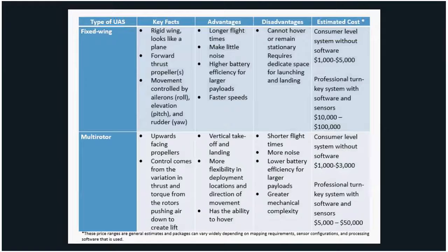Sure. Yeah, this is George. So it depends a lot on a few things. One of them is that if you didn't fly with an RTK system like Sam talked about earlier, it would be necessary to have some ground control points using a survey grade GPS to get accuracies to measure the height of, you mentioned grass.